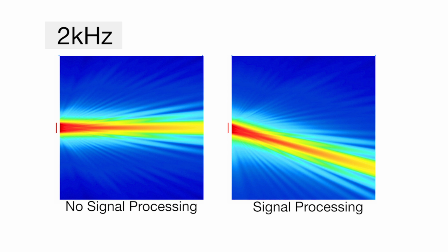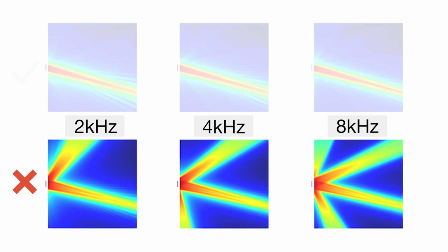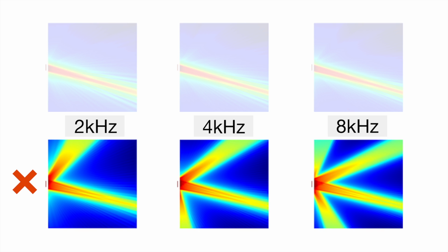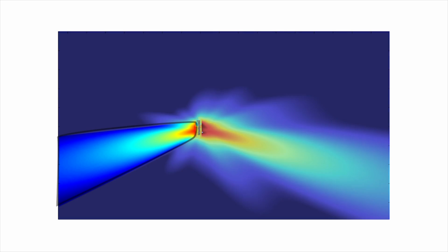It's possible to modify the directivity with signal processing. However, with omnidirectional array elements, the spacing between them and the signal processing for each element needs to be properly implemented. This is not easily accomplished. When it's not, grating lobes can be unintentionally created. And side lobes can emerge in problematic locations.